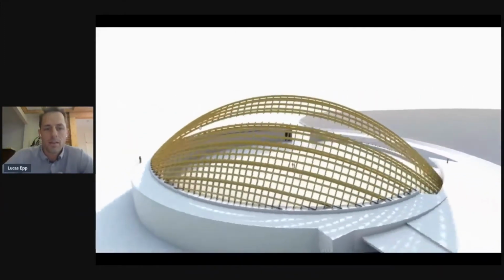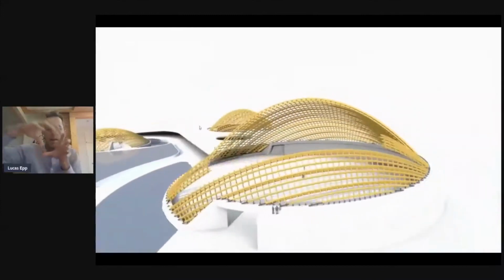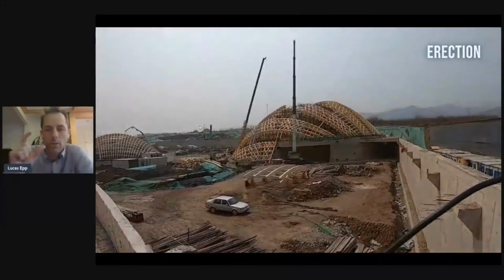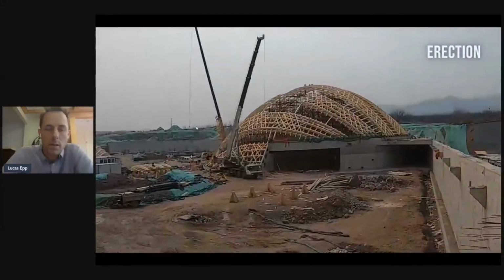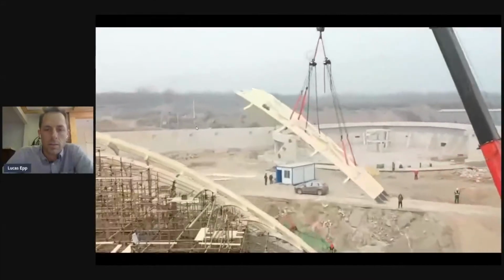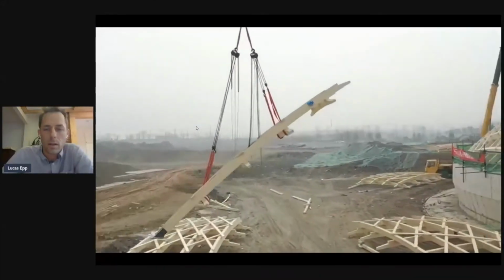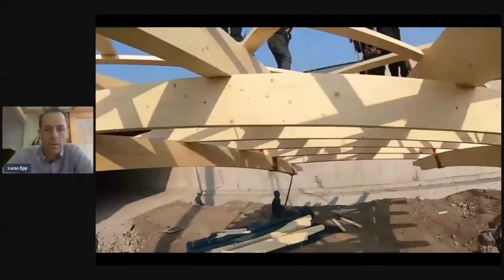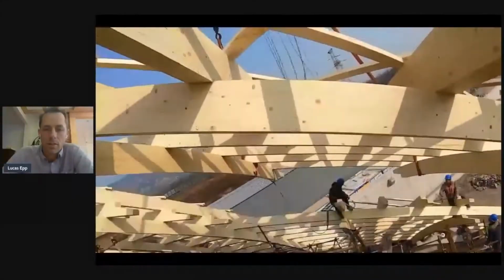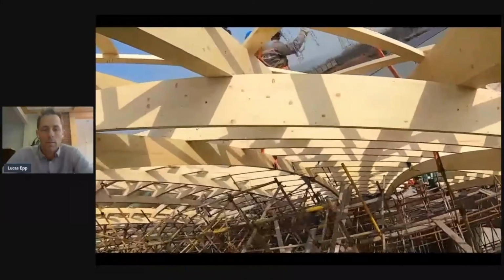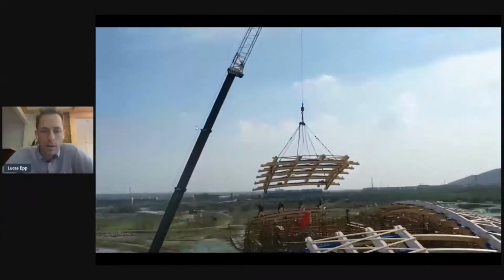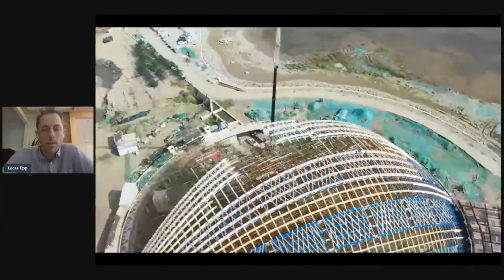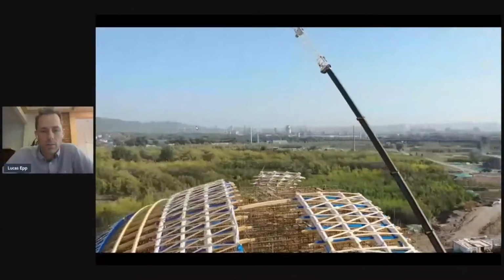On the installation side, you can see we're creating these lines of prefabricated panels and then infill strips in between, which gives us the ability to control install tolerance. This is on site in China. We had several engineers and site supervisors controlling the whole installation, but this installation process is going 24/7 in China. It's a totally different speed of construction to what we're used to here in North America. There are hundreds of workers working all day and all night, and you can only control so much. So you have to have rigid quality control procedures in place and documentation of the actual construction process.